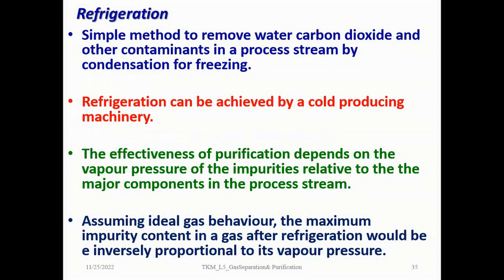Assuming ideal gas behavior, the maximum impurity content in a gas after refrigeration would be proportional to its vapor pressure. So the lower the vapor pressure, the more it will be separated, right?